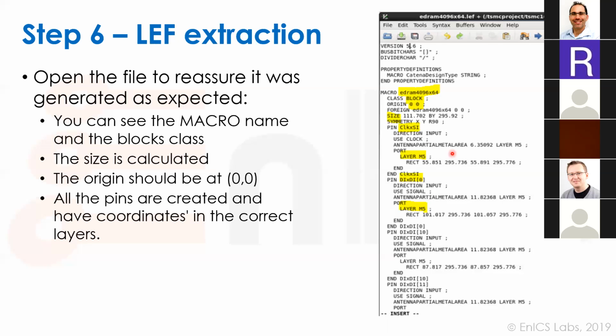To build on what Adi had just explained, in the fabrication world this is known as IPC, in-process charging. The mechanism is just like Adi said, it's damage due to the charging of the interconnects during the plasma processing steps in the back-end layers. You get charge accumulated on the metal lines that act as antennas or as collectors. So you have voltage that is generated and accumulated, and the accumulated charge can potentially discharge through the gate oxide. So that's the physical mechanism.